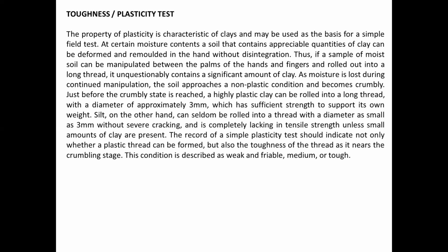The record of a simple plasticity test should indicate not only whether a plastic thread can be formed, but also the toughness of the thread as it nears the crumbling stage. This condition is described as weak and friable, medium, or tough.